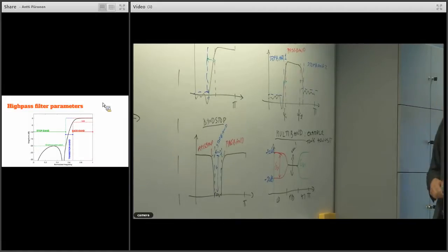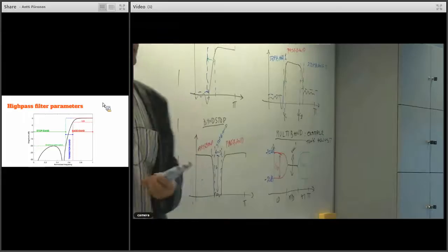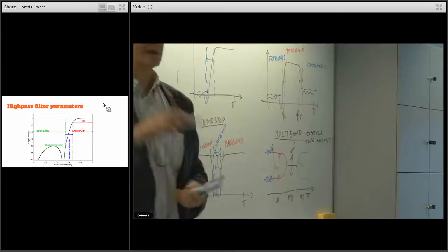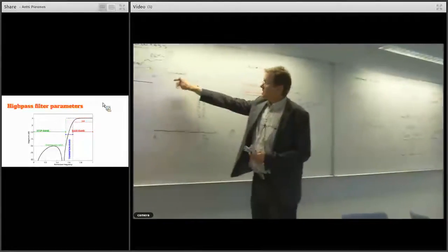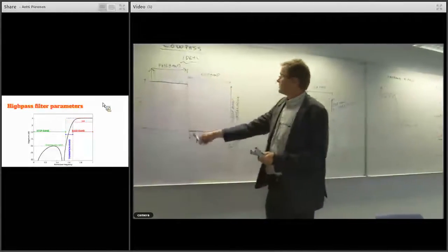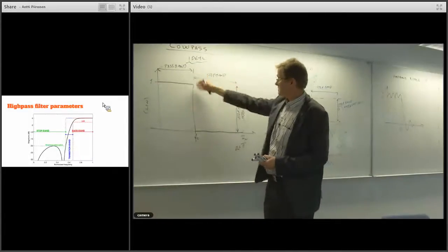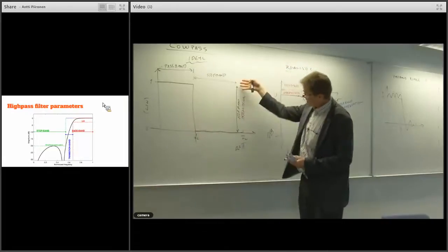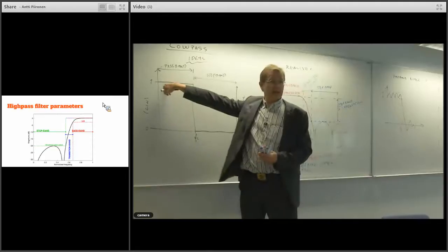Okay, good. So those are the fundamental filter types by the frequency response, or more specifically, amplitude response. Low pass, ideally it's a box which has just a single passband, and then immediately after that passband, at the corner frequency, the stop band starts, with infinite attenuation in the stop band and unity gain in the passband.